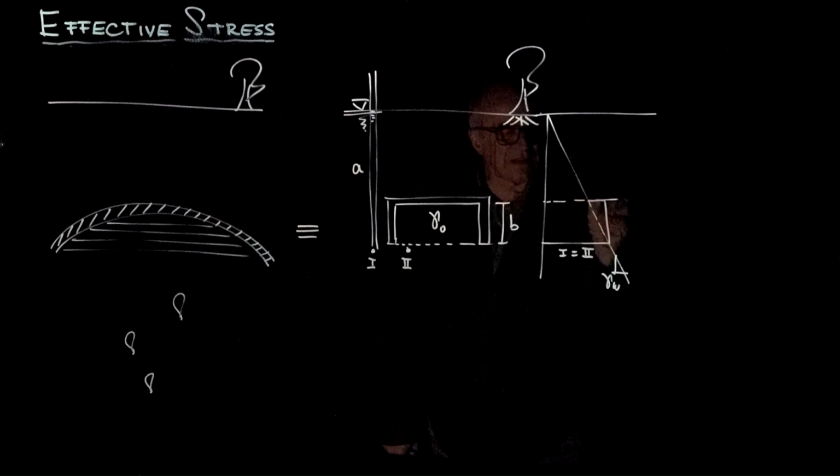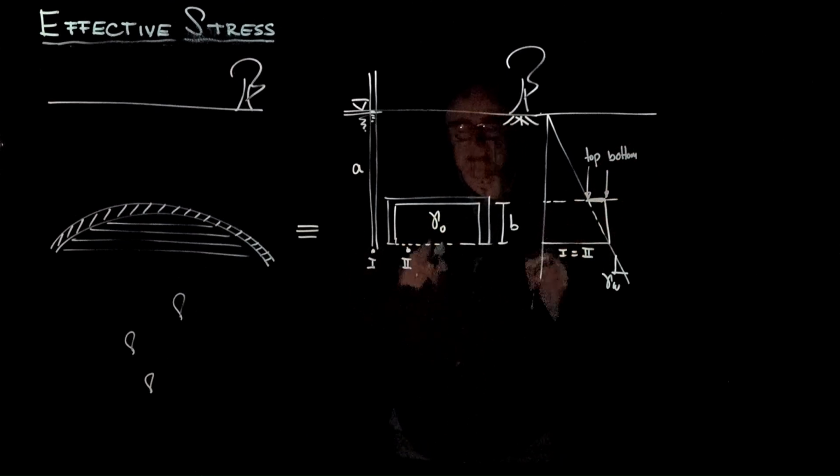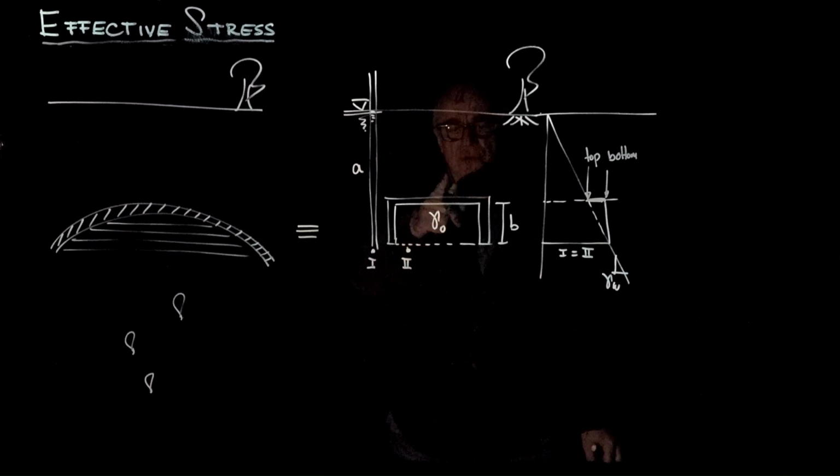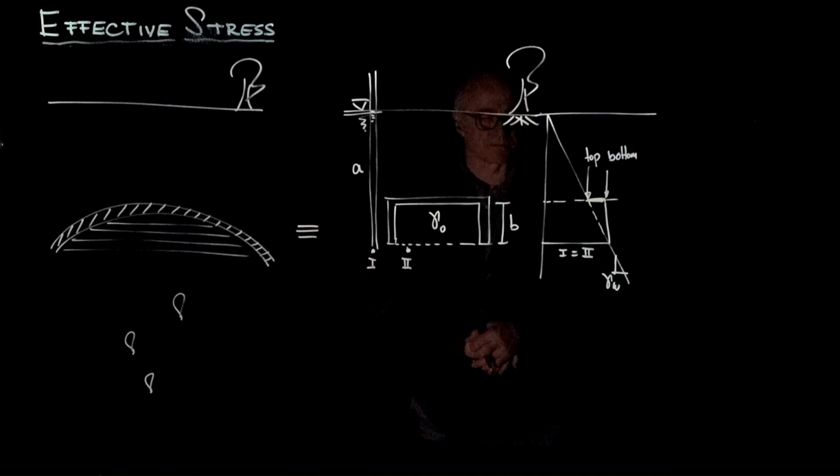So notice that against the seal, I have this pressure from the top of the seal, and this is the pressure at the bottom of the seal. And this is the one that is going to drive flow through the seal, and the one that is going to create capillary resistance until the seal fails to properly store the fluids.